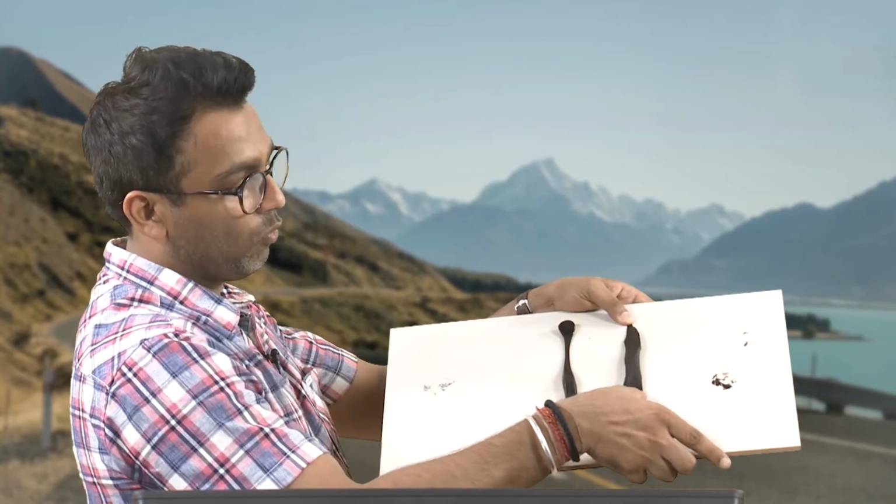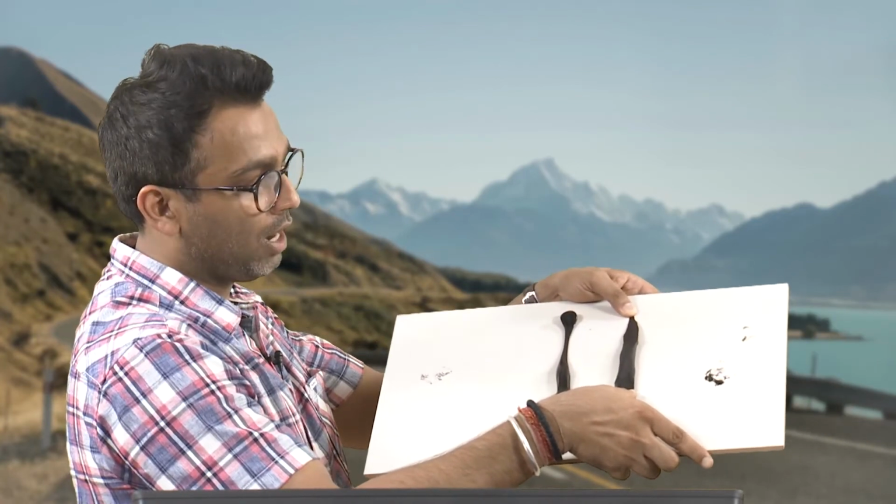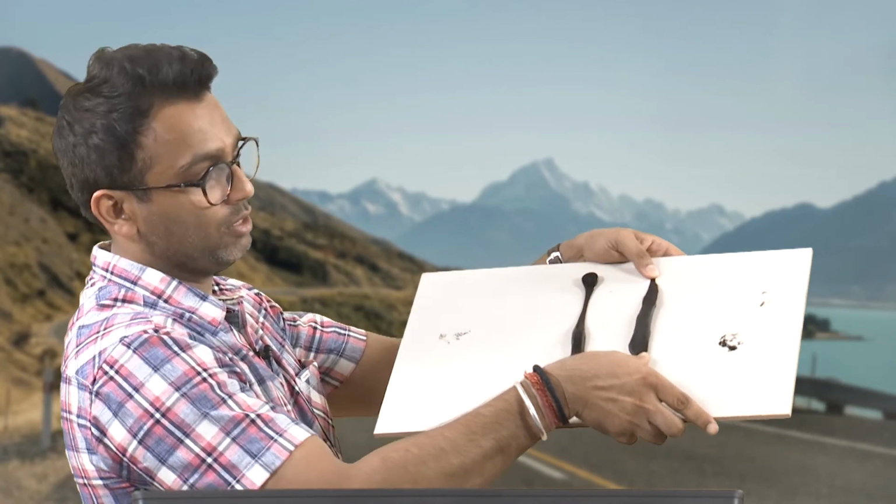The same I am doing with this, I am stretching it almost to the same distance, alright. Well, I have to apply more pressure because this is a modified bitumen, same distance, and again I am keeping it on the slab. Okay, so, you see I am trying to stretch. The one which I am not holding is the conventional bitumen, and this is the modified bitumen.